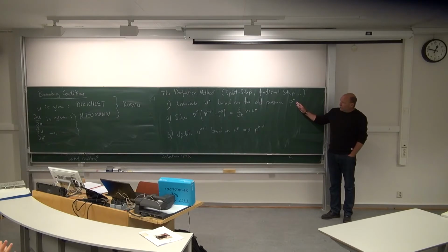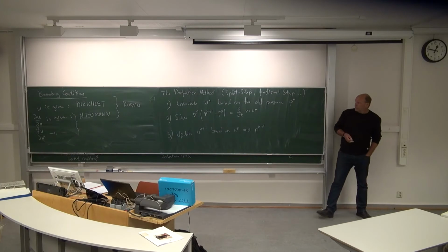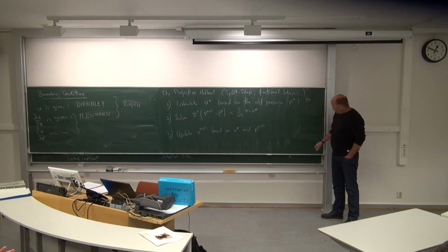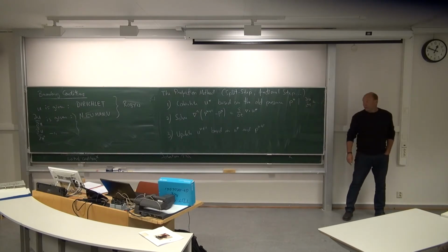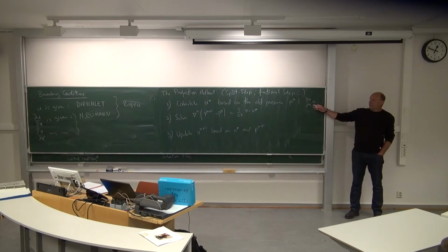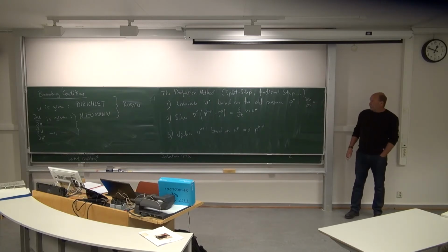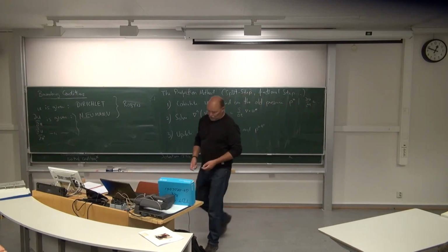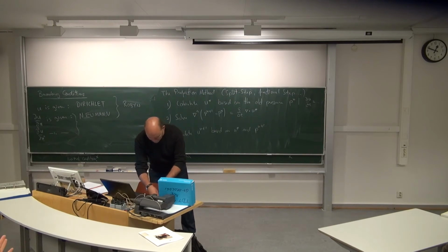This equation here, updating this tentative velocity field, that is a parabolic equation. It looks something like this: du dt equals, and then actually just known things on the other side. So we just update it directly. We need the boundary conditions, of course, and for the first step you need also the initial conditions. But that was not a problem at all.